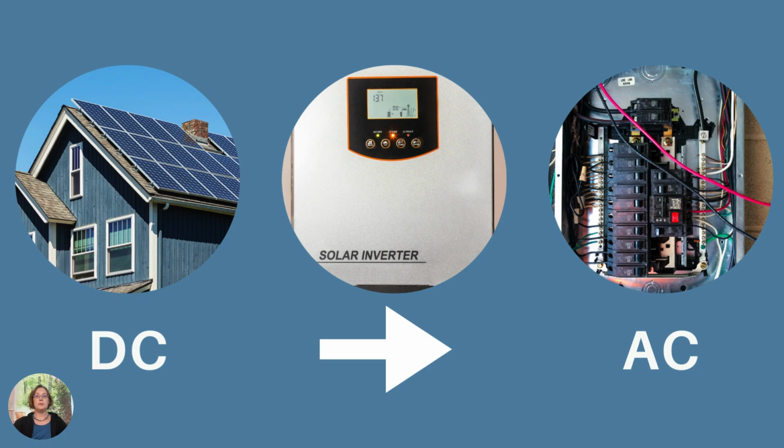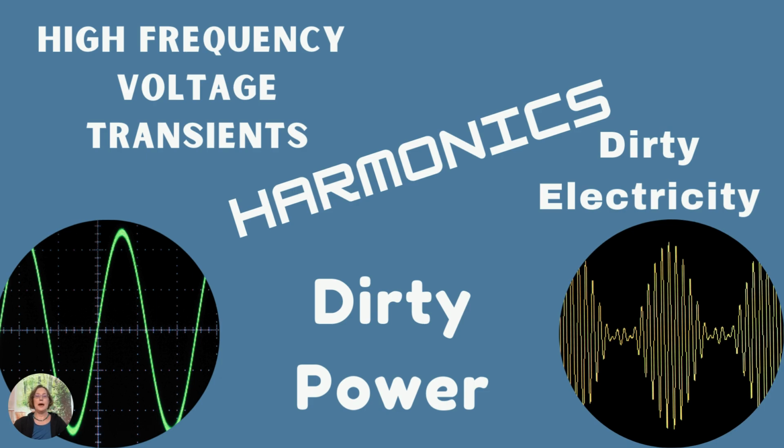PV inverters use pulse width modulation switching to transform power from DC to AC. This controls the magnitude and the frequency of inverter output and eliminates low order harmonics. On the other hand, it does generate high frequency harmonics. You might ask, what are high frequency harmonics?